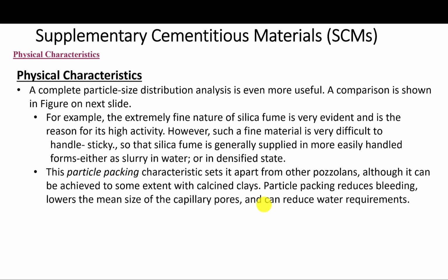Okay, but it is not unusual to find some large agglomerated particles that have not been dispersed. So, using silica fume in the concrete has to be done with care and with certain methodology to make sure we get full benefits of it.